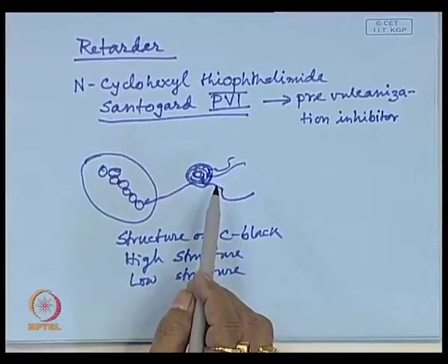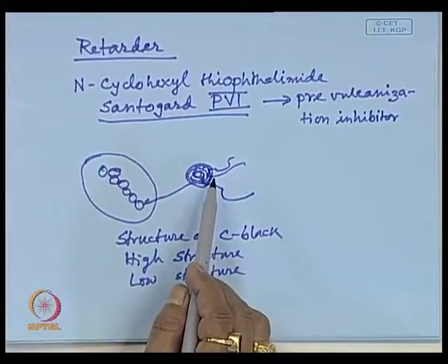This is in brief the mechanism of how reinforcing occurs. You must have seen wild fruits with thorny surface in the childhood days, probably you have played with those things, throwing them on the hair of your friend. It sticks to the head, on the hair, thorny surface, it is like that. That means, if you put carbon black in rubber, what will happen? The ends of polymer chain get occluded, go inside and get anchored, and once anchored, it is difficult to separate from there. So, this is the phenomenon, occlusion and anchorage, and this gives physical anchorage.